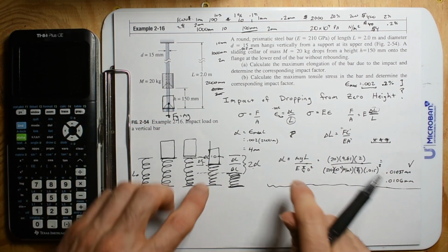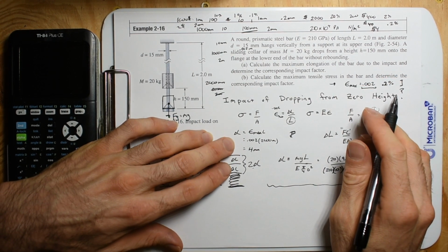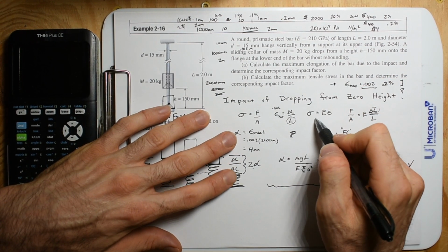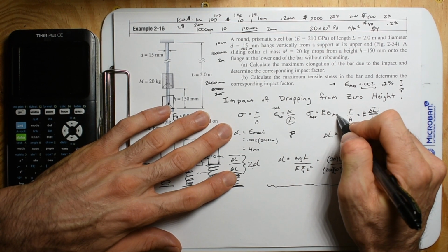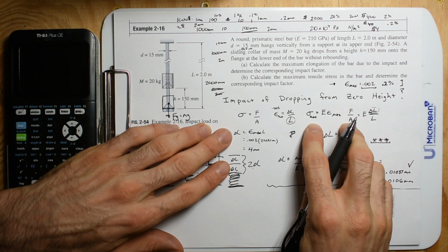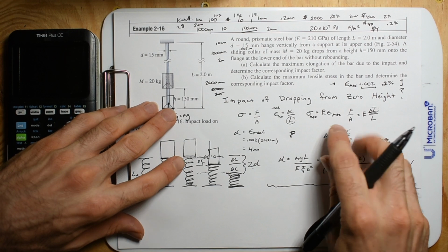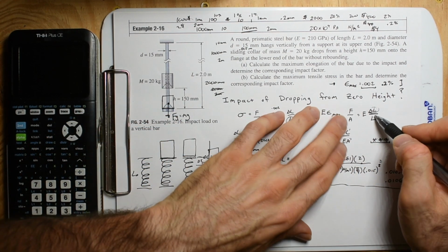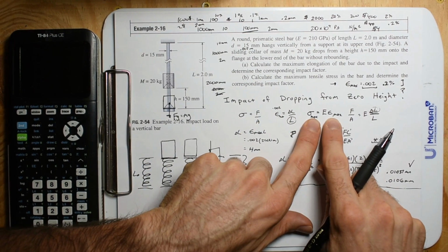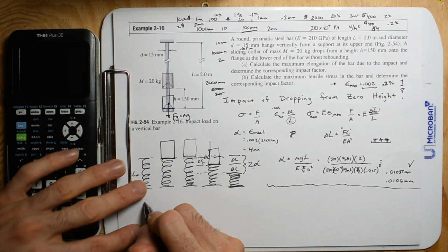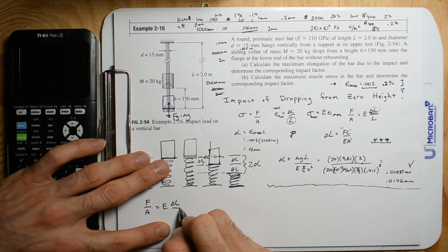Okay, the whole reason I was doing this is because from that we can get a check on reality. Because we can also find the strain max. And sometimes finding the max strength isn't super useful. Like sometimes we might want to find the max force. Well, you have this equation, and let's talk about this. Because once you get these two and then this relationship, you can throw all these together. So let's rewrite this one. We have F divided by A is equal to E times change in length divided by L.